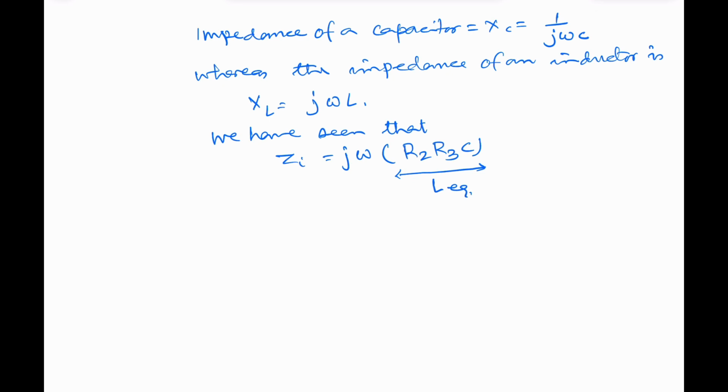So इसको समझने के लिए ज़रूरी है कि आप डायग्राम को पहले अपने सामने रखिए, और उससे मैंने जो निकाला है स्टेप बाय स्टेप, तो आप उसको फॉलो कर सकते हैं आसानी से. So मैंने जैसे पहले बताया कि an inductor has a large size and this cannot be incorporated in an IC chip which is very small in size, but its property can be achieved using operational amplifier, and we have shown that. If you use a capacitor in place of ZF there, you get the property of an inductor.